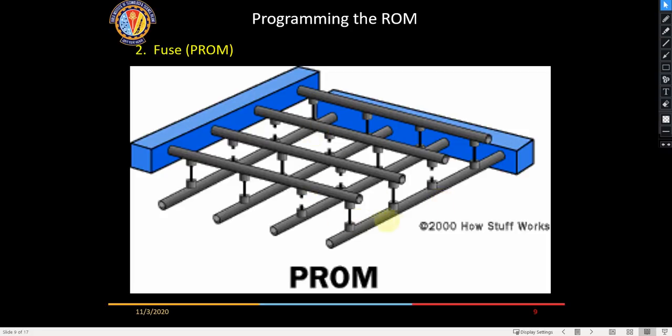But if you see here, it is not related with power supply. Even if there is no power supply, it would still work, right? It is not power supply dependent. That is the great advantage. And also it is pretty fast. If you see, all these connections are hardwired, so it will operate extremely fast compared to any other ROM or hard disk. It doesn't require power supply. The only problem is it is not programmable; it can be programmed only once. So that is okay.